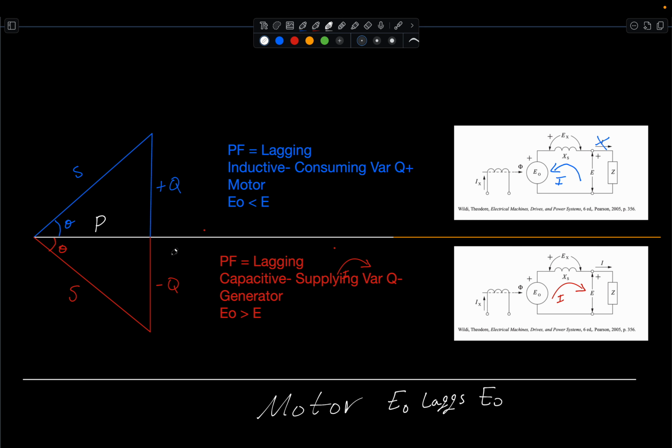reactive power. So what I did here, and one thing I forgot to do, is your theta is measured by theta V minus theta I. What this really means, since we always reference the voltage at 0 degrees, is that when given a power factor at, let's say, 0.8 and it's lagging, let's just go ahead and solve to find the angle.